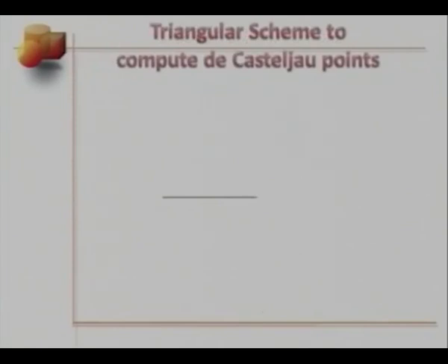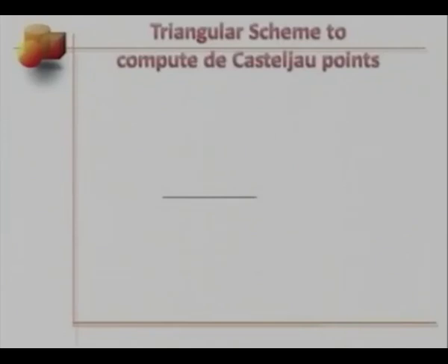Coming back to de Casteljau's approach, there is a very nice triangular scheme to compute the intermediate de Casteljau points. Let's see how. The first thing we need to do is arrange all the design points in the first column: b_0^0, b_1^0, b_2^0, and we keep on going, b_{n-2}^0, b_{n-1}^0, and b_n^0.